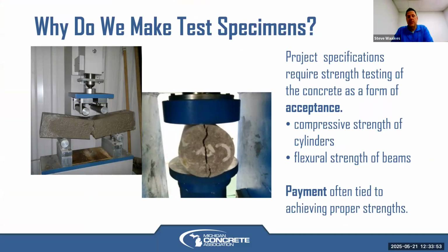We've always done it, kind of like the slump test. And it gives us as engineers, and I am one, a good sense of, okay, at least it's strong enough to resist the loads. And for pavements, slabs on grade, curb and gutter, concrete floors, sidewalks, drive approaches, driveways, when it's on an aggregate base or some sort of prepared subgrade, it's fully supported. Its strength is generally not a concern, even if you have low strength.